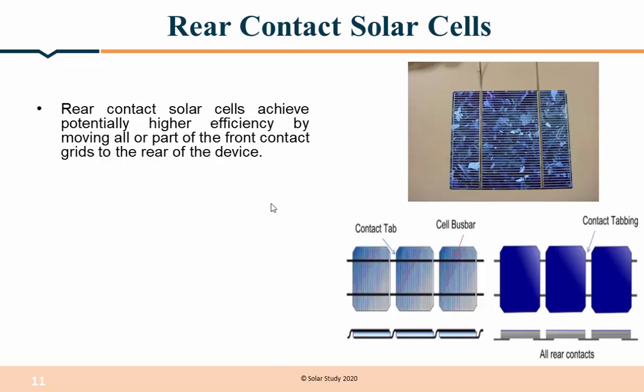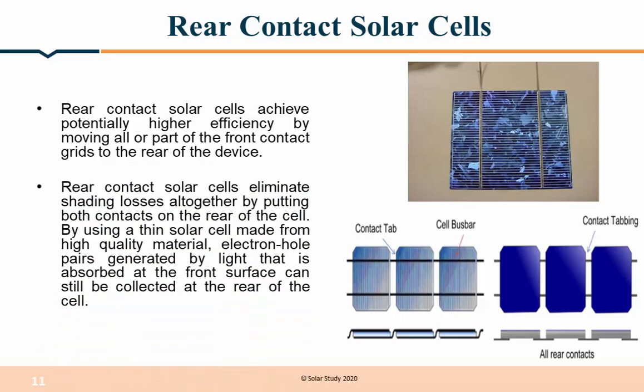In this image you can see there are so many types of contact that can be done. As I told, some people make contacts using silver paste only for a few fingers, and from here a few fingers, like this they are made. Then finally one aluminium contact will be formed. So these are the different types of contact to the solar cell.